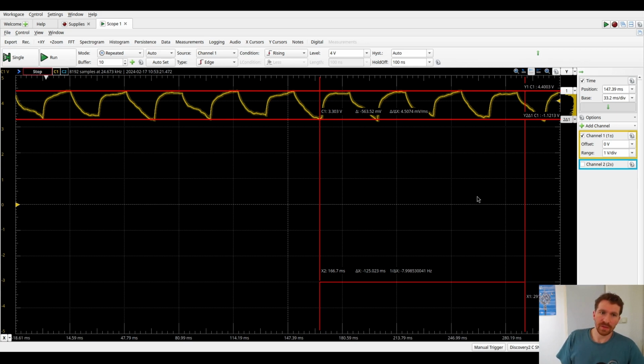Something we could do is to process this signal a little bit. So try to remove this offset, so you can see that the signal begins and ends all the way up here at 3 point something volts. We could pass that through a capacitor and recenter that on 0 or reground that, and then amplify the signal that we have, and that way we could actually use it. But that's going to take some more components, and it's going to be a little bit more involved as a device to get set up. But that would work as well.